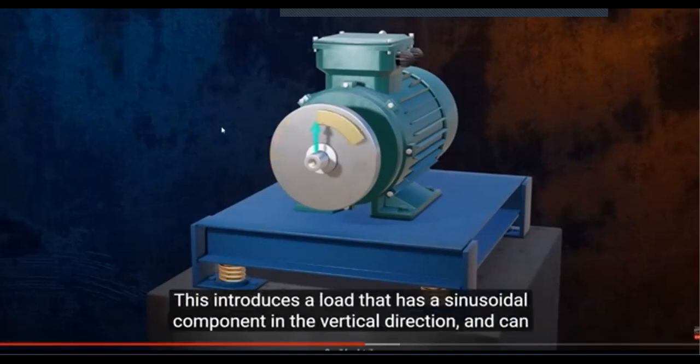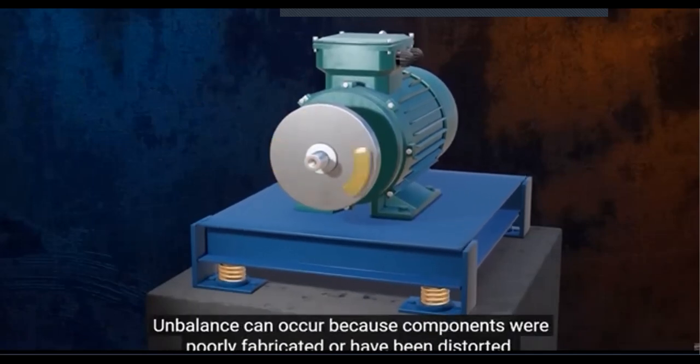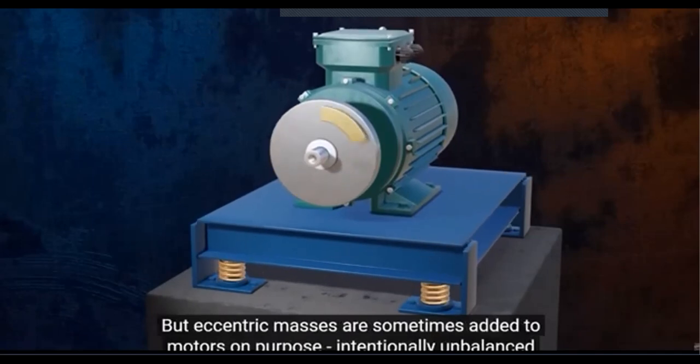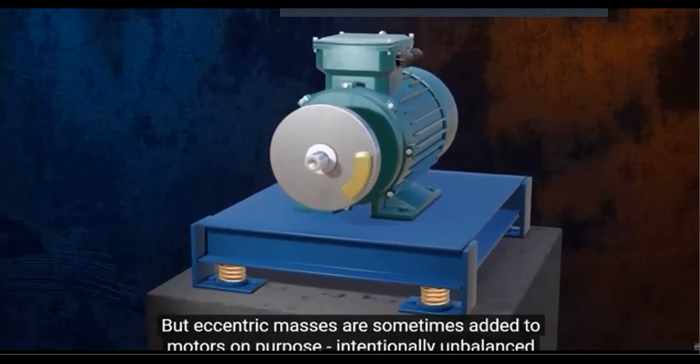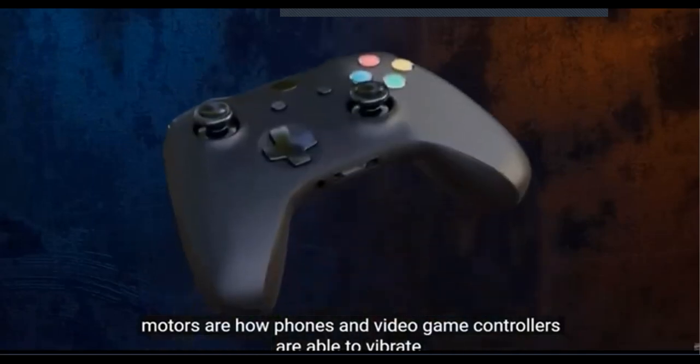This introduces a load that has a sinusoidal component in the vertical direction and can cause vibration. Unbalance can occur because components were poorly fabricated or have been distorted. But eccentric masses are sometimes added to motors on purpose. Intentionally unbalanced motors are how phones and video game controllers are able to vibrate.